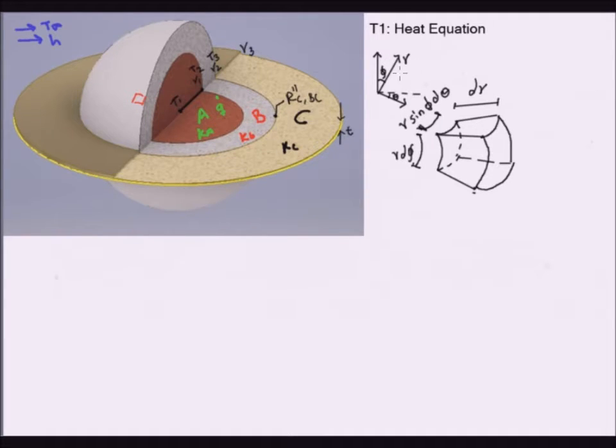So in spherical coordinates, you define any point using the vertical angle phi, the horizontal angle theta, and a radius that is pointing in the direction of these 2 angles. So by drawing 2 surfaces that are slightly displaced by a small increment in each of these directions, we end up with something that looks like this figure here. In this differential control volume, we can label the quantities for our energy balance.